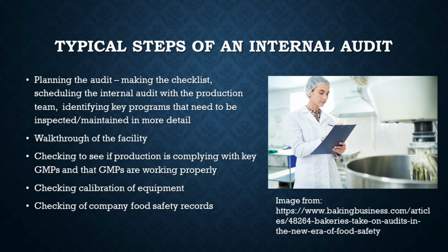And then the other two big components are first checking the calibration of equipment. So one pretty normal routine in more so in QC than QA, I think in the general sense, but I've had to do this for most recently my current job and also my first one. Whether it's a scale, a temperature monitoring device, lab equipment, really anything that requires any degree of accuracy and precision, that needs to be serviced every year, maintained for calibration to make sure it's accurate. So you want to check the schedules for that, both on paper and as you're looking at the tags that are usually on the equipment as you walk through the facility.